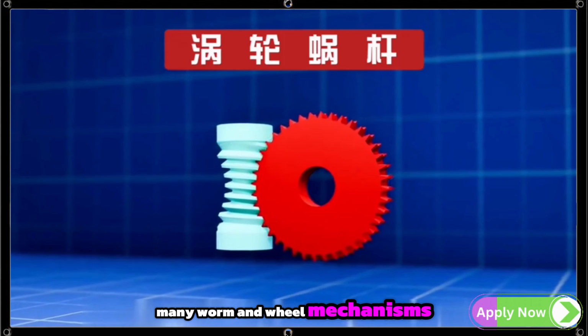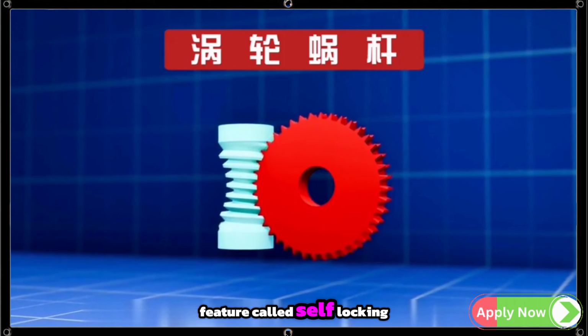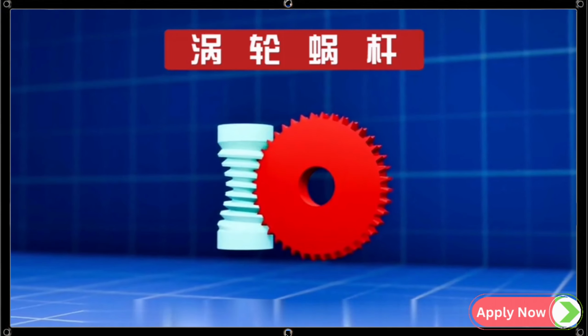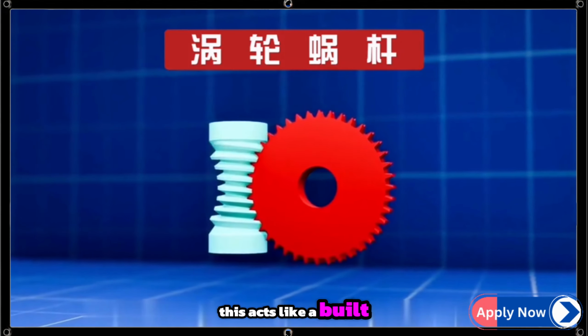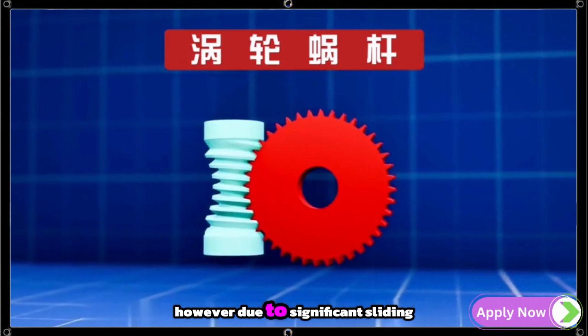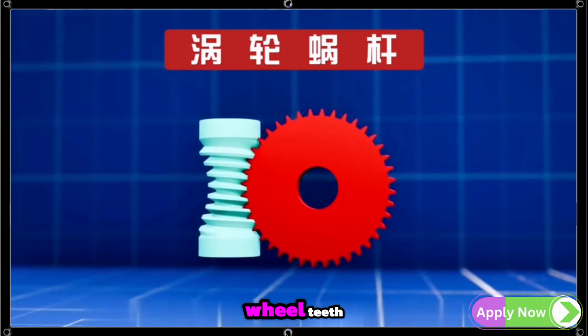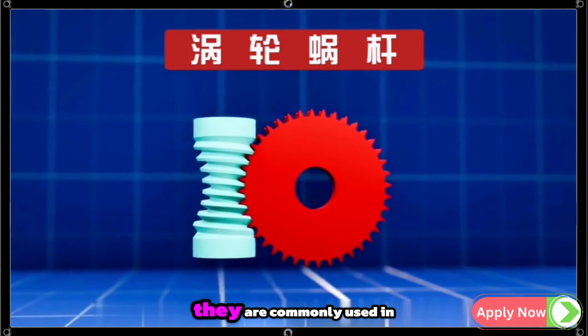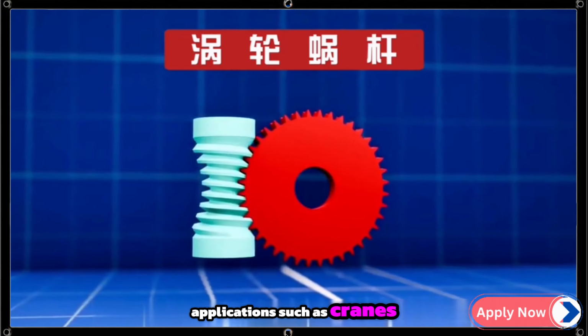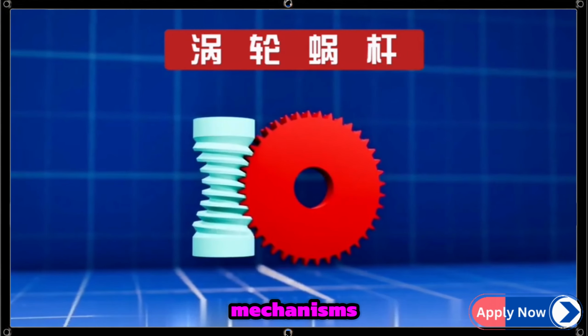Many worm and wheel mechanisms have a unique feature, called self-locking. This means the worm can easily drive the wheel, but the wheel struggles to drive the worm in reverse. This acts like a built-in brake. However, due to significant sliding friction between the worm and wheel teeth, worm and wheel systems are generally less efficient than other gear types. They are commonly used in applications such as cranes, conveyor systems, and fine-tuning mechanisms.